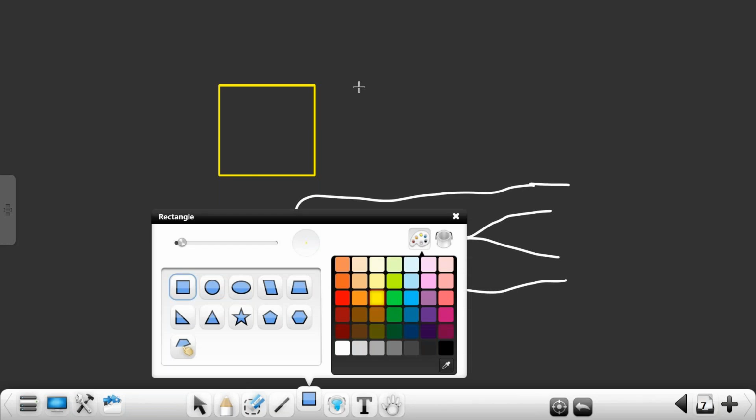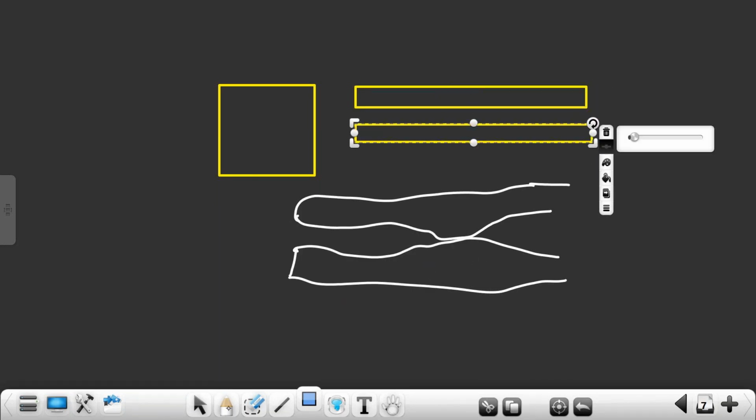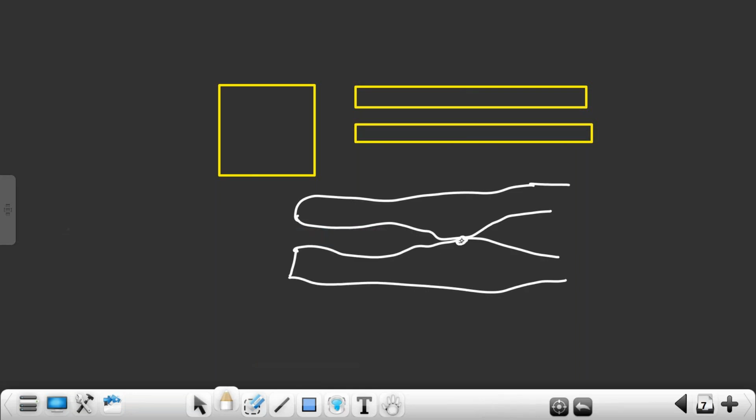Our expectation is to have the metal layers like this. But what is happening here? Both are shorted here. Even the foundry will not know that it is shorted. So this is the error in the foundry, in what they're fabricating, because everything is happening in nanoscale. There will be closely placed metal layers inside an IC. They cannot check every IC, every metal layer, to see whether it's fabricated properly or not.